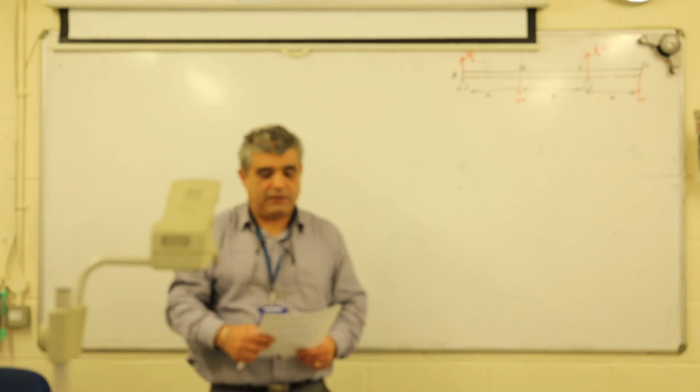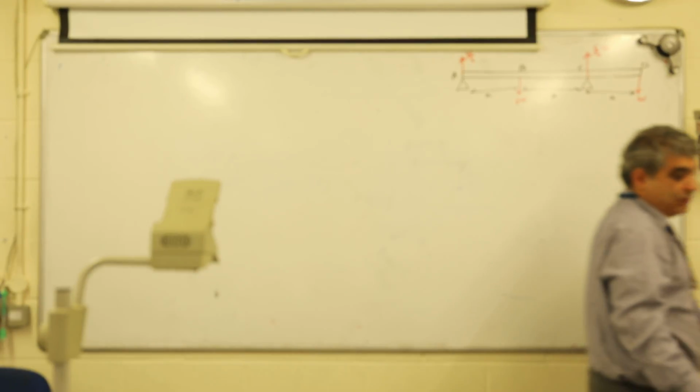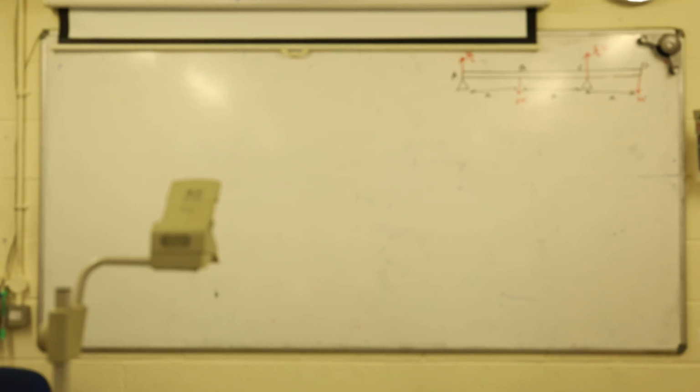Right. Now, the second step which you have to do, now consider the shear force S and bending moment M at the point P on the beam, where AP is equal to X. Do you remember what I have done? It means you have to start cutting the beam across. And when you do the cutting, before and after each concentrated level. Does it make sense? Yes.